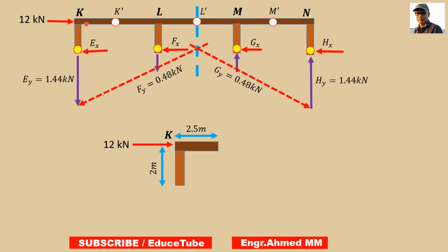So first I took this because the lateral load is working here. Normally we start from the place where the lateral load is working first, so I have taken this. Now we need to find the reaction components at this position and this position. So first, I will put here the column axial force 1.44. We already received it here, so surely we can write this.